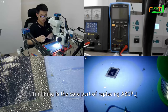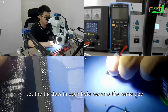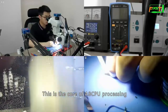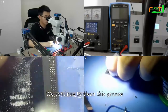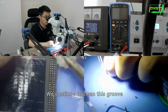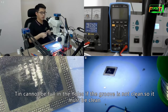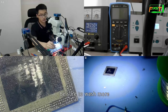Tin filling is the core part of replacing the A8 CPU. Let the tin dots in each hole become the same size. Not one big and one small, some high and some low. This is the core of A8 CPU processing. We continue to clean this group. Tin cannot fill the holes if the group is not clean, so it must be clean. More cleaning does no damage to the CPU. Be sure to wash more.